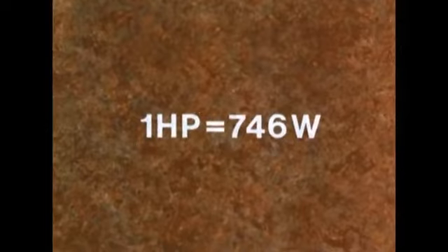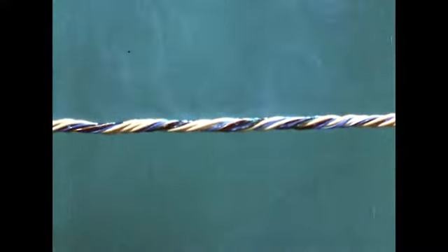Finally, a word of warning. This is a sight you should hope never to see again. An electric conductor is smoldering. But it can happen, like this. Most conductors use the power they absorb to make heat, but they are usually electrically insulated. And this insulation also tends to keep in the heat generated, so that unless we are careful, the conductor may get overheated and damaged.